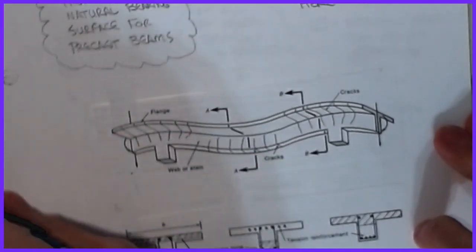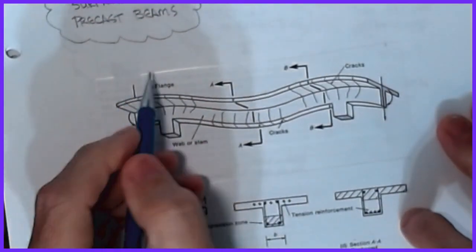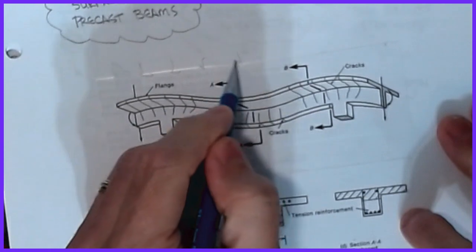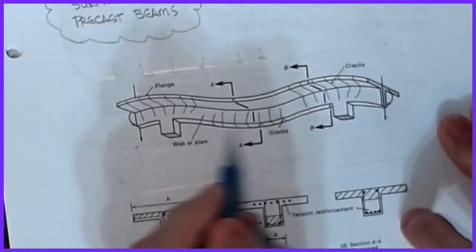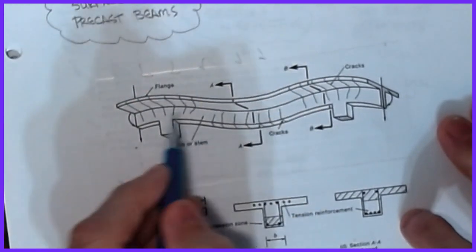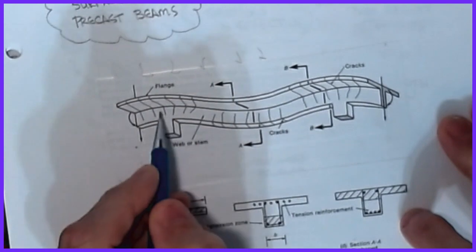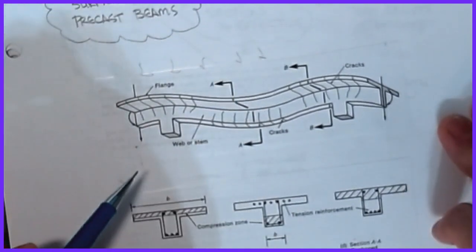Okay, all right. Now, if you look, this is kind of what we're describing about these moment reversals. If you look at the crack patterns, I'm assuming I have load acting down along the length here. In the middle of the region, I would get cracking in the middle, which means reinforcing needs to be at the bottom. And then coming over the supports, with these continuous effects, I would get cracking in the top, which means I would need the steel in the top. And so the way that we analyze these will be a little bit different.